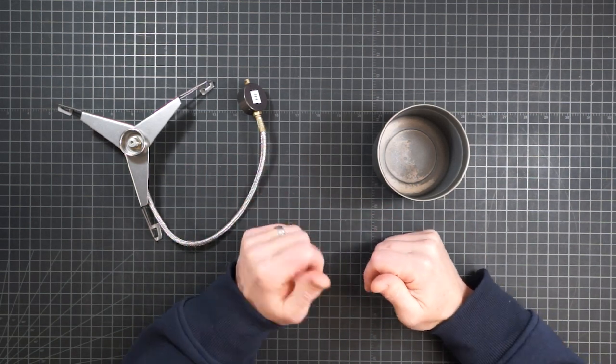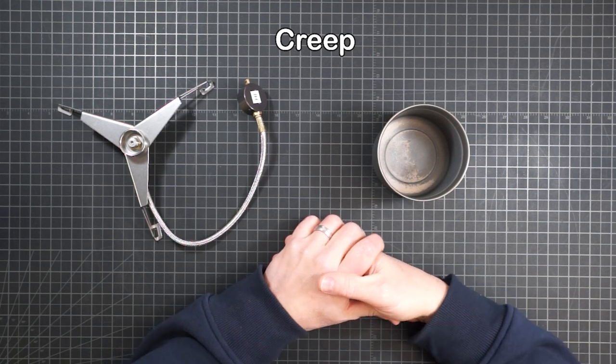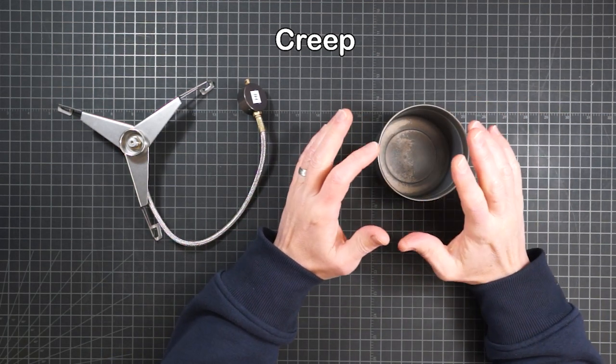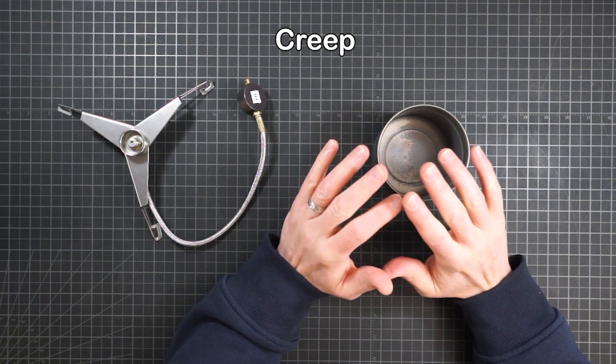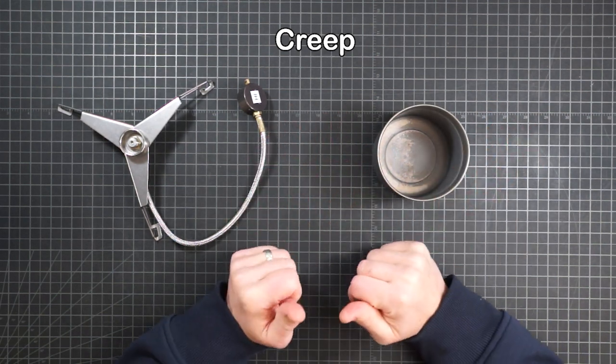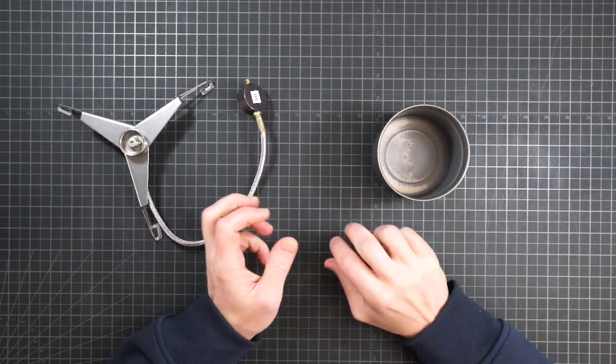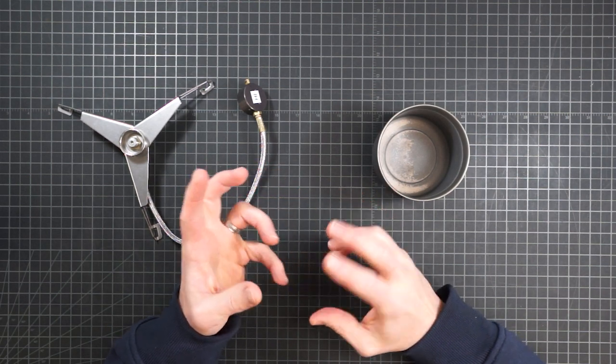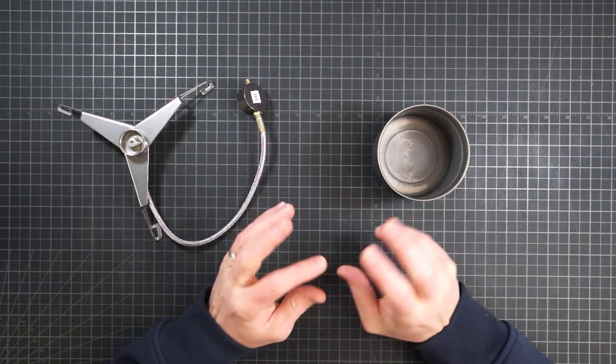To make matters worse, there also appears to be creep. After an adjustment, the results will continue to change over the next several tests as the apparent friction in the system slowly gives way over time. So put all that together and it becomes an extremely frustrating situation of constantly over or undershooting the target.